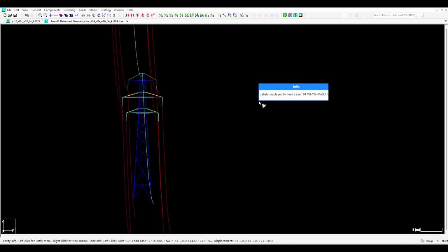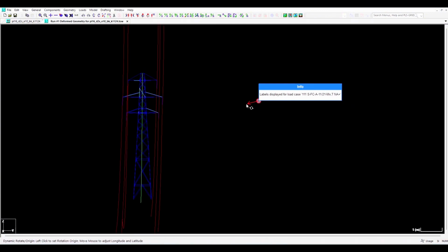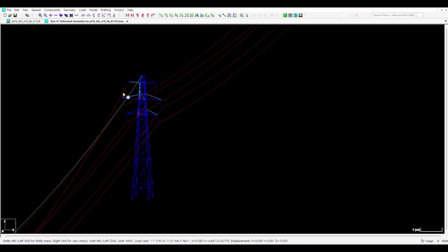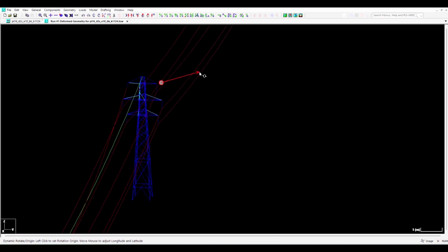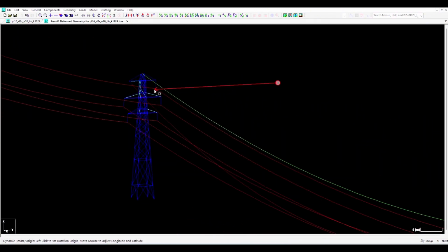So again, as we can see, all the bars are below 100% utilization. This is a really good sign. So I'm hoping that when we do add the point of connection, whether it be to a pole, to a gantry, to a point of connection mast, the tower will be able to withstand the loads.